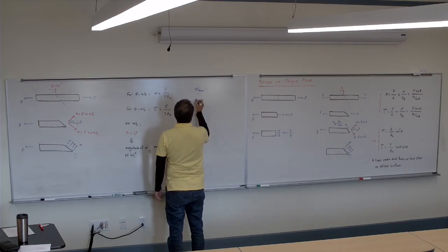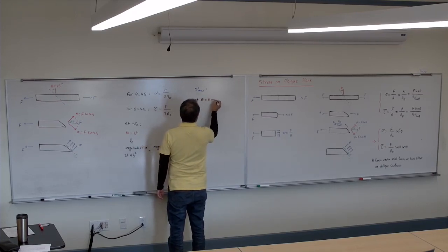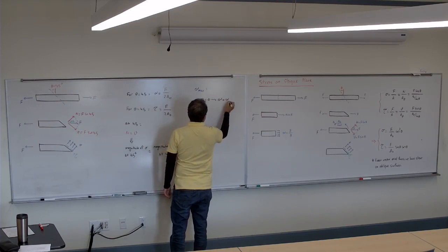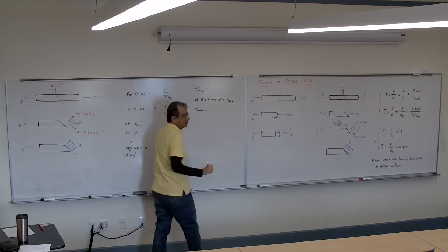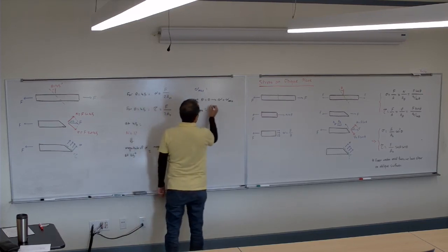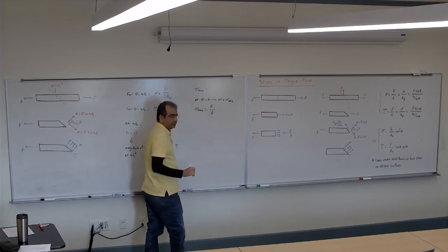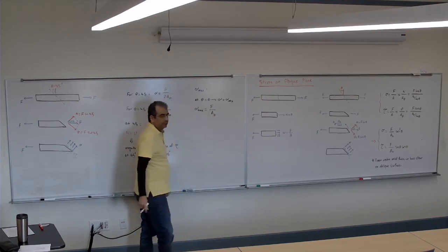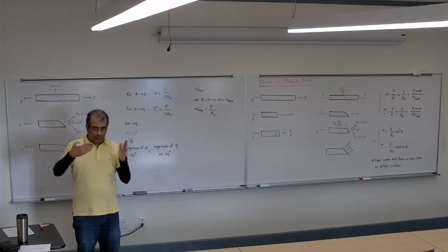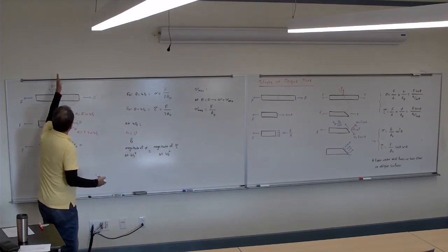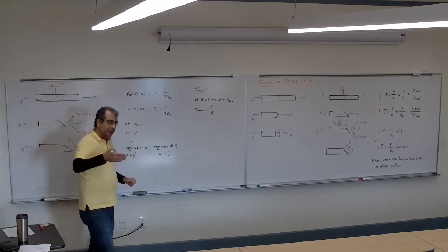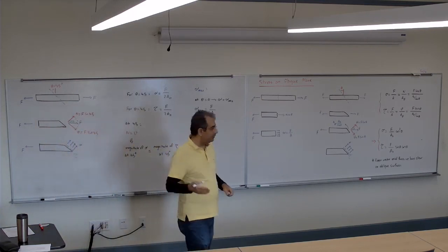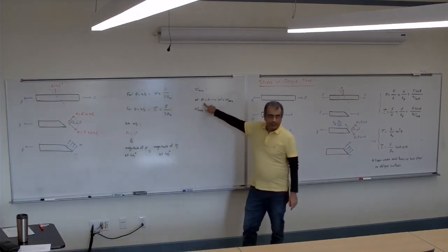So at theta is 0, sigma becomes sigma max, and the sigma max is equal to just F over area A naught. So if I cut it normal to the surface, the sigma is maximum. If it wants to break under the normal stress, it will break at theta 0.